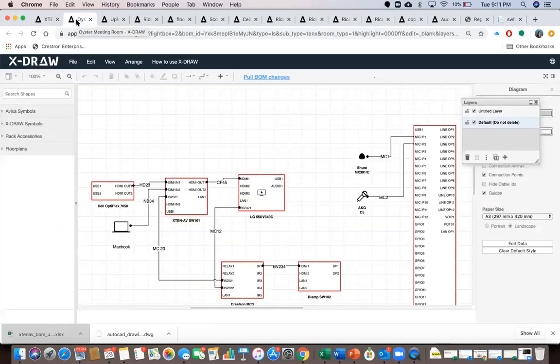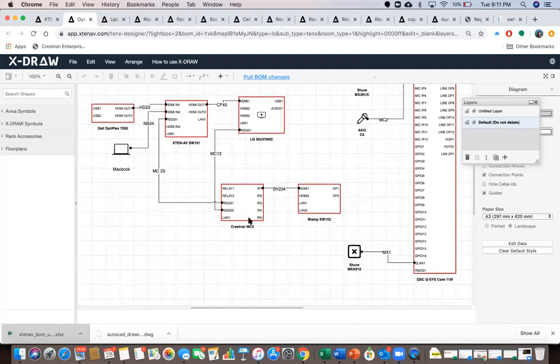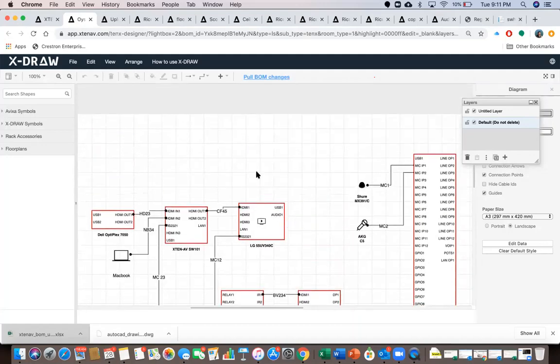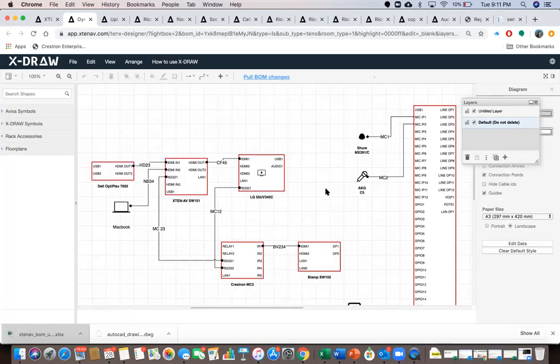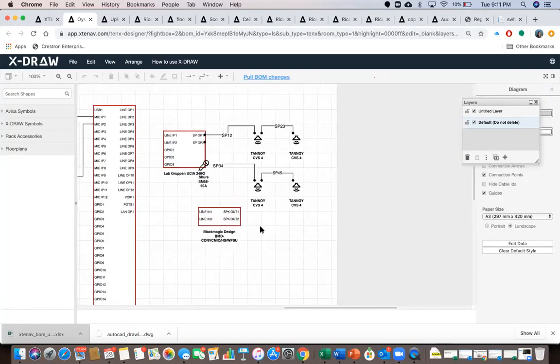And the second one is your drawing window. You will see that the connections right now are created here because it's an existing design, but you will find all these blocks under 3 different sections, video, control, and audio, and you will have to make the connections yourself. So here are the products which I have added in this design.